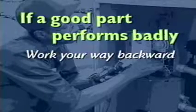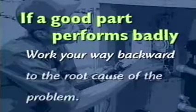In this case, keep working your way backwards until you get to the source or root cause of the problem. You know you're at the end of the troubleshooting trail when you find the malfunctioning part or circuit or condition that caused all the symptoms. That's the root cause. And when you find it, you can then move on to step 5.